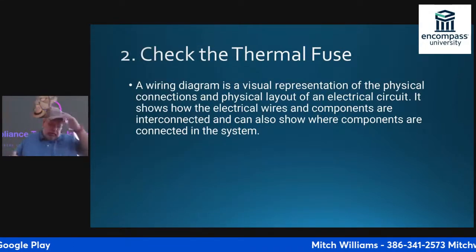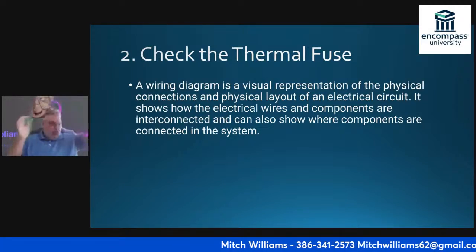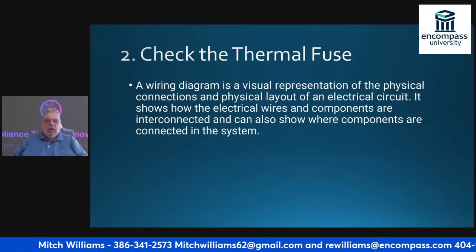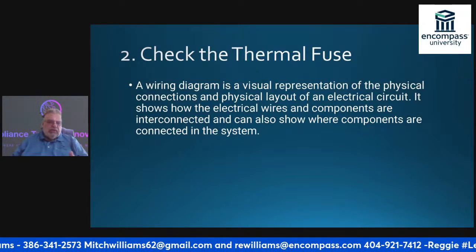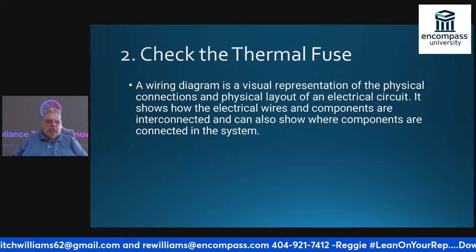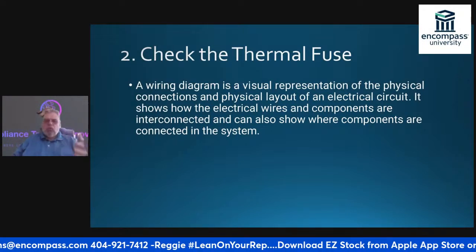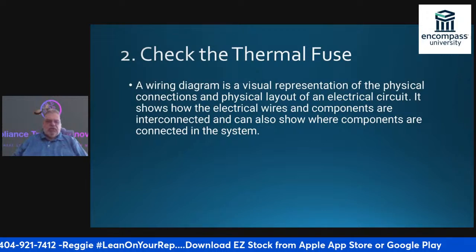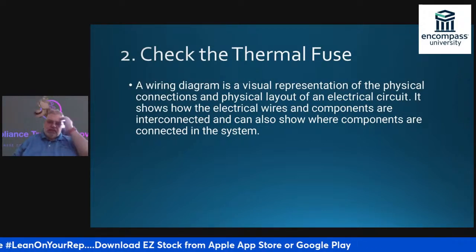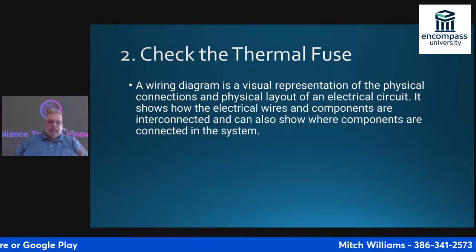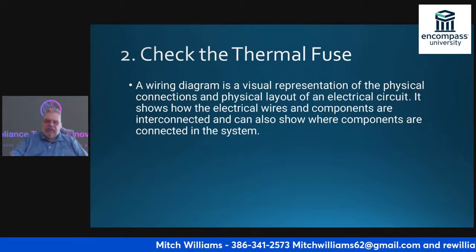Then if all of that checks out, what I'm going to do is check the thermal fuse. I'm sorry, guys. It's a little warm in here. So I'm going to pull the wiring schematic so I can get a visual representation of the physical connections and the physical layouts of the electrical circuit. It will show me the electrical wires and the components that are interconnected, and can also show where the components are connected into the system.